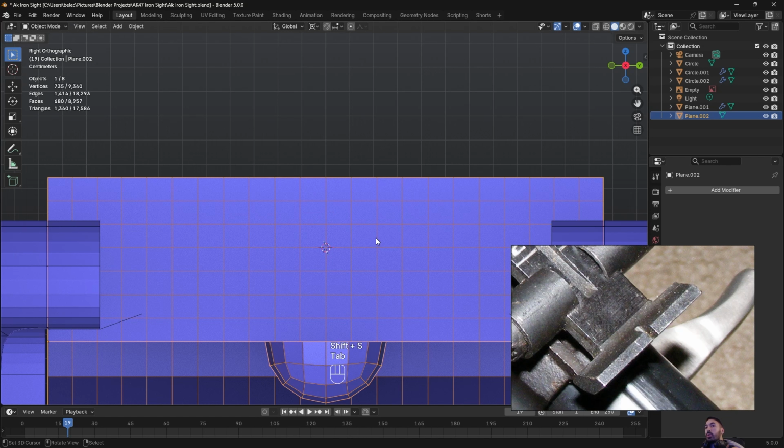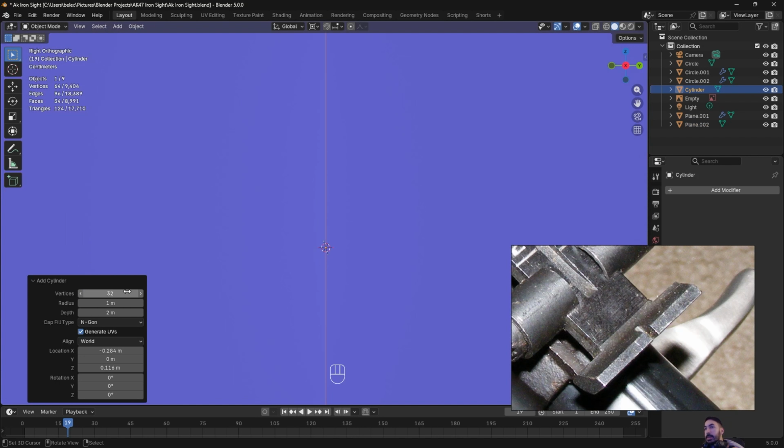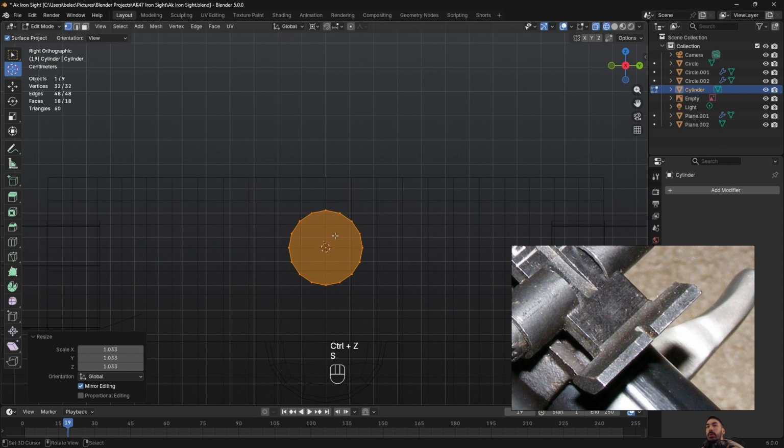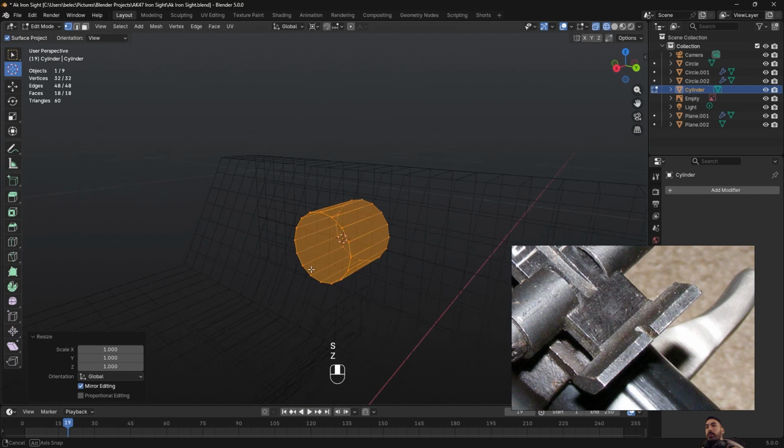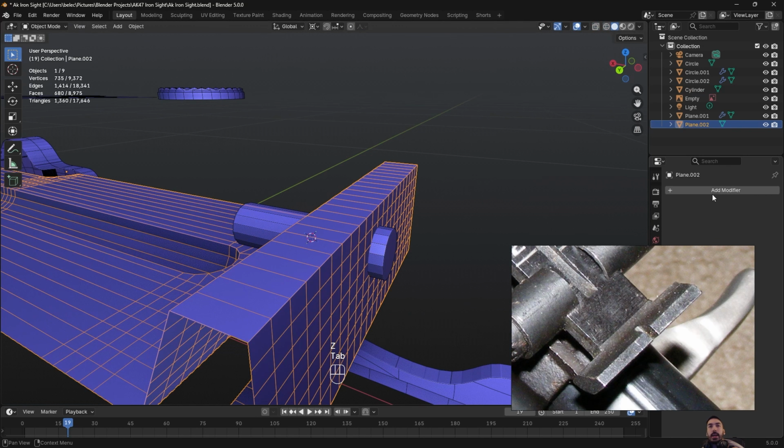So we place the 3D cursor over here, Shift A, give me a cylinder with 16 vertices, align it with my view, make it just slightly bigger than a 2x2 surface on the background, scale it up on the x-axis, add modifier, generate boolean, target the cylinder.